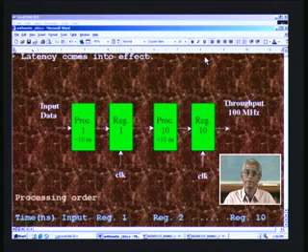In this case we need to apply fresh data every 10 nanoseconds, in the processing order, and that is how you get a throughput of 100 megahertz. This will be clear if you follow this processing order.